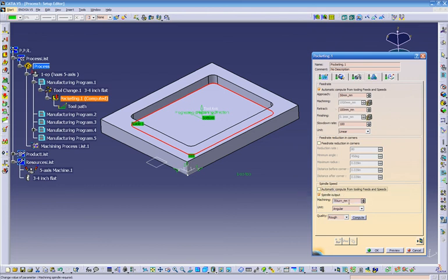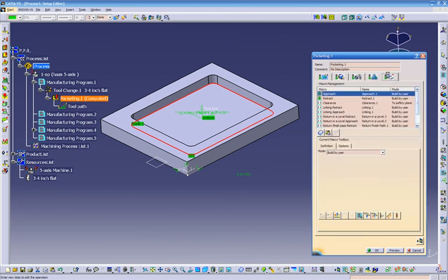And this is our RPM. So for the 3/4 end mill, if we have a carbide, we'll usually go around 6500 RPM. And let's put the quality of this program finish. We want a nice finish on this part. Let's go to the last tab, feeds, the way we lead in and lead out of this part.